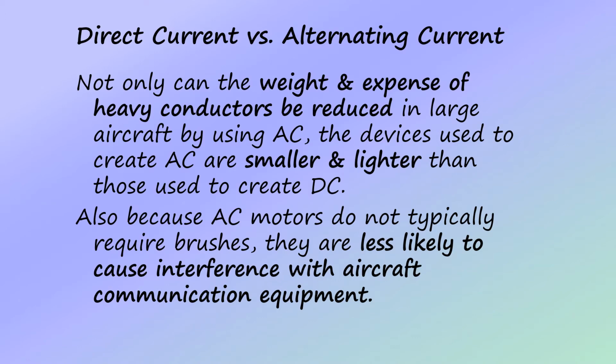Most of our smaller aircraft operate on direct current only systems. Many larger aircraft, however, incorporate alternating current power into their electrical systems. Larger aircraft can require many miles of electrical wiring. The A380, for example, requires 2,000 miles of electrical wiring. Because through the use of transformers, alternating current power can be transferred over smaller gauge wires than can direct current power, saving weight and the expense and space required of heavier gauge wiring.